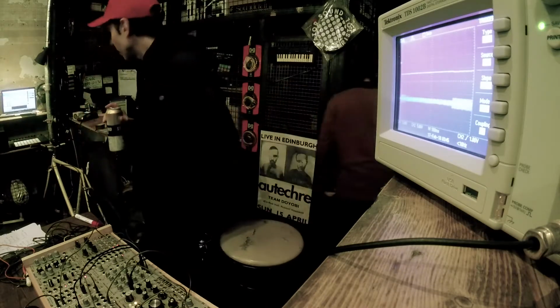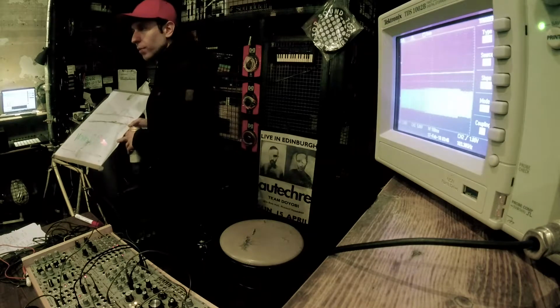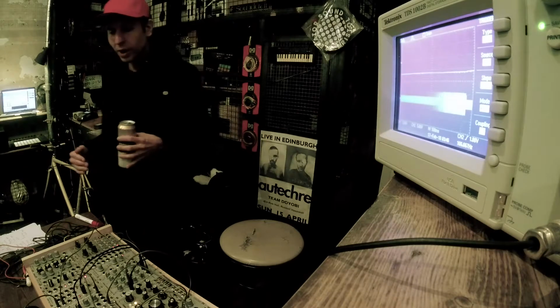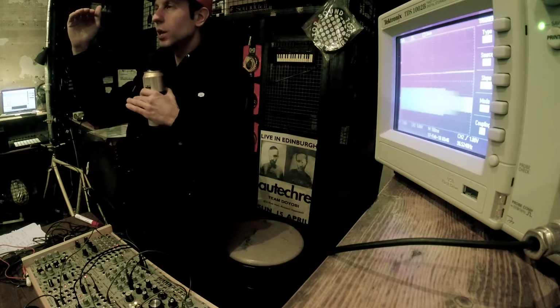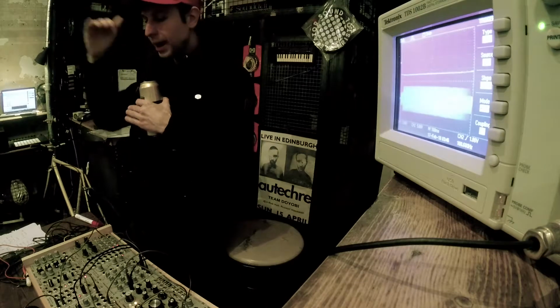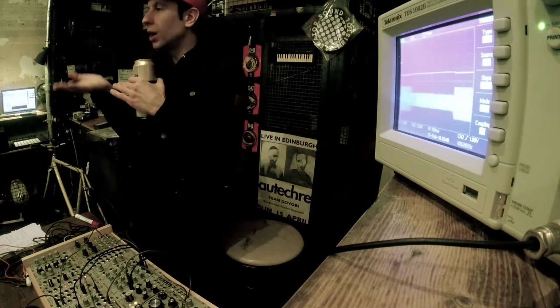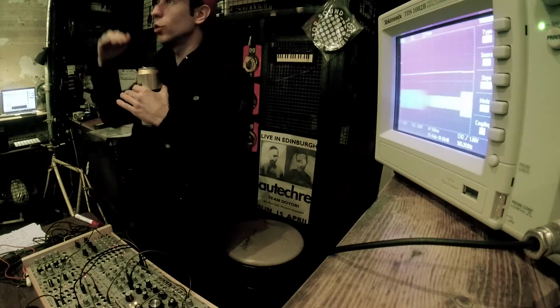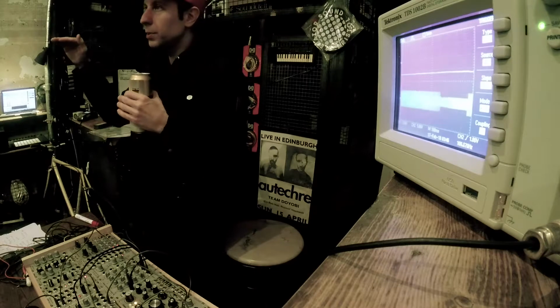Okay, so how about you guys in the meanwhile try to sketch this patch? See if you can make a data flow block diagram which does this. So let me just repeat what we're doing. We have a noise, quantized noise. What we're doing with the min-max module is pushing the lower clipping level up such that only the tops of this noise come through and the bottom is clipped.